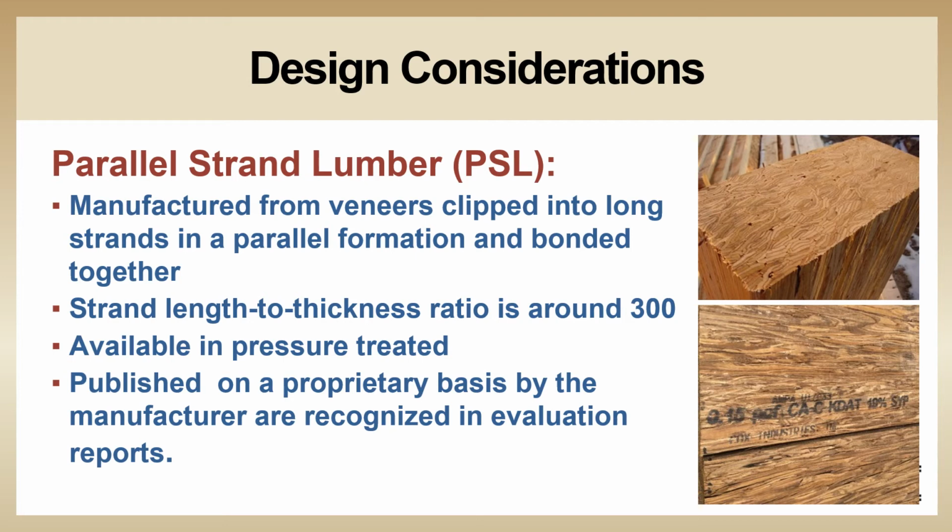PSL is manufactured from veneers clipped into long strands laid in parallel formation and bonded together with an adhesive to form the finished structural section. The length to thickness ratio of the strands in PSL is around 300. Like LVL, this product is used for beam applications where high bending strength is needed. PSL is also frequently used as load-bearing columns.